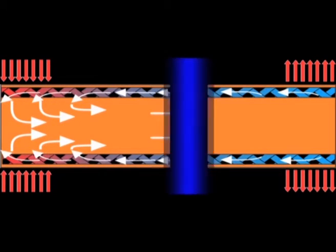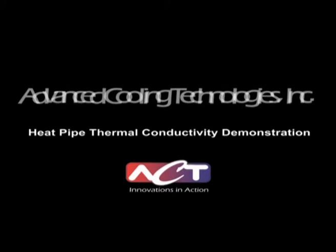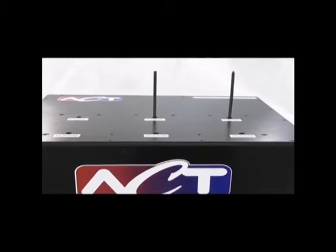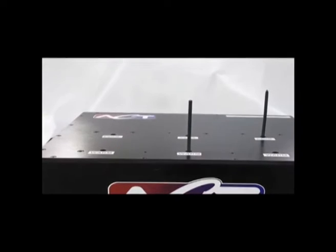By utilizing liquid and vapor phases, the heat transport is extremely efficient. Because it's a closed-loop system, heat pipes operate continuously and passively, creating a very reliable component in your thermal management system. Now we'll go through a quick demonstration on heat pipe thermal conductivity. In this demo, we'll examine the heat transfer capability of a copper rod versus a heat pipe. On the outside of both samples, there's a paint that changes from green to yellow when the temperature exceeds 40 degrees C. We'll now place the copper rod into the hot side of the unit and let it heat up.